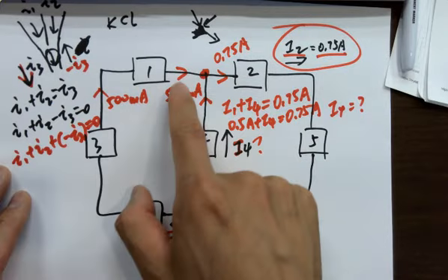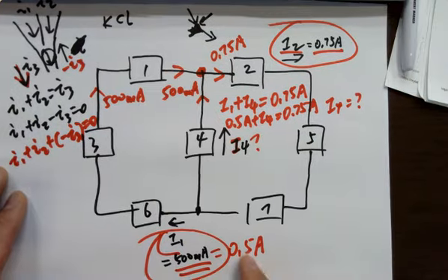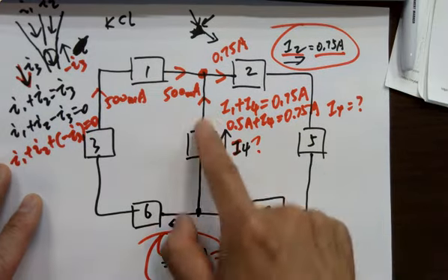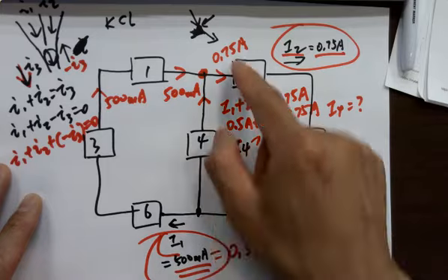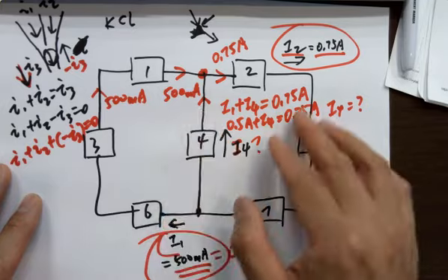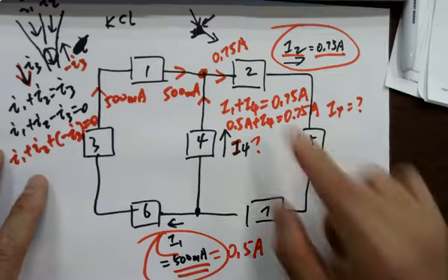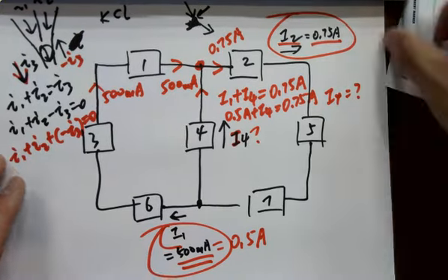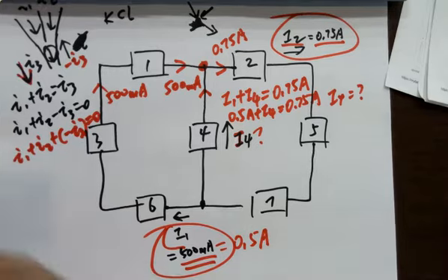So this is going in, which is I1, and that is given. This one is going in too, but it's not given. You are calculating this one, and this is going out. So you have one variable and three currents in here. Two are given, one is variable. You can calculate it using this equation. Is that clear? KCL.